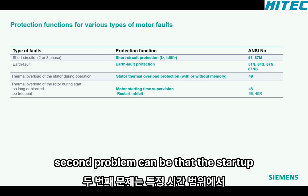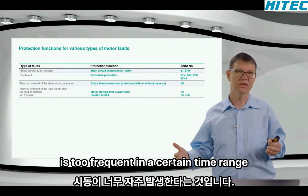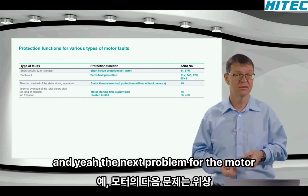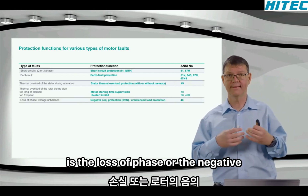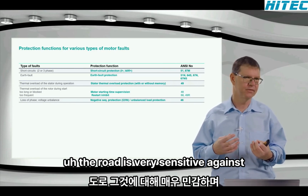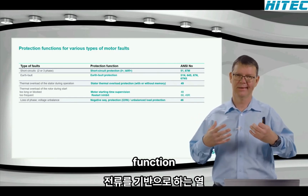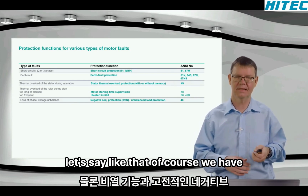The second problem can be that the startup is too frequent in a certain time range. For this, we have another function, the restart inhibit function. And the next problem for the motor is the loss of phase or the negative sequence current on the rotor. The rotor is very sensitive against that. And for this, we also have a thermal function based on the unbalanced load current, let's say like that.